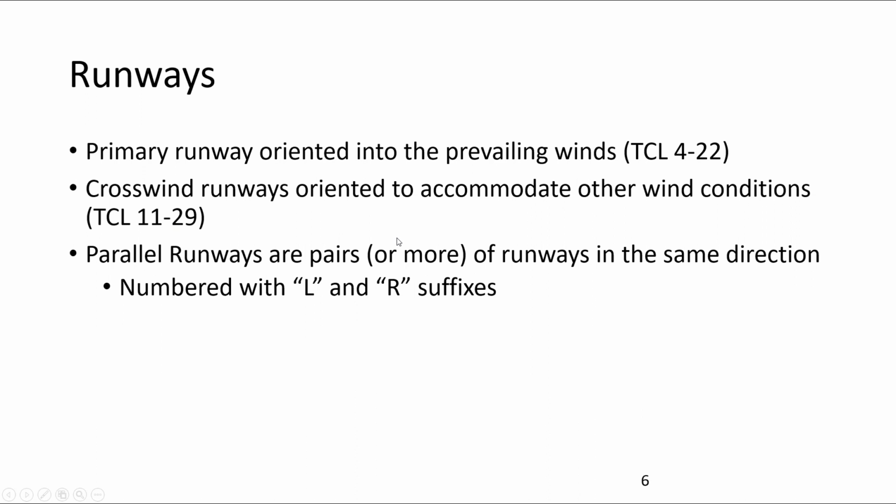Crosswind is dangerous for airplanes, and you can imagine it can blow them off target. If you've got a wind coming in from a 30-degree angle off the center of the runway, you have to turn a little bit sideways to keep going in a straight line compared to the ground, so you have to vector that force versus what your engines are giving you. They call that crabbing. You don't want too much of that, right? There's a maximum amount of crosswind that an airplane can handle, and the FAA lists that for us. And so we try to aim our runways into the prevailing wind.